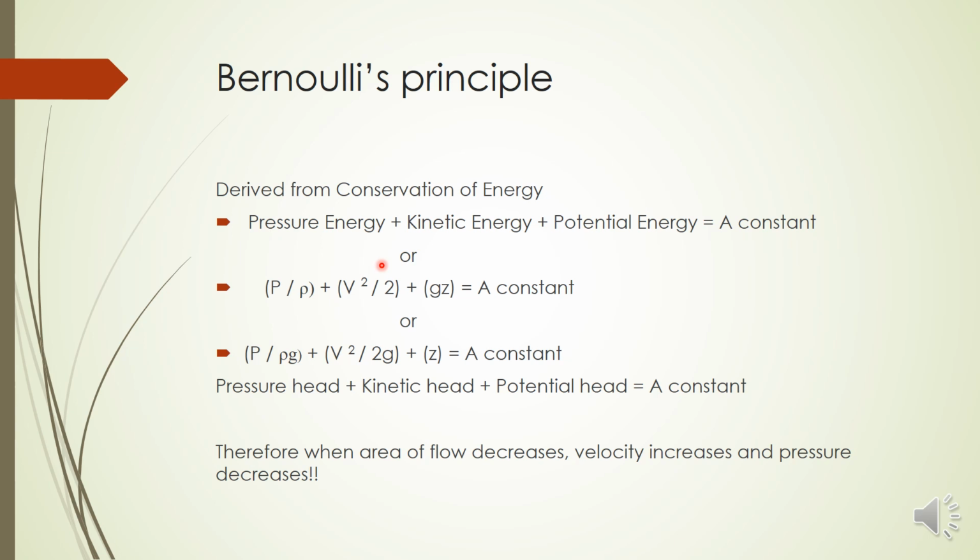So that means the potential energy is a constant. If the pipe is at the same level, the potential energy is constant, so you can neglect that term. So that means if area is decreasing, velocity must increase and simultaneously pressure must decrease. So that is the final answer.